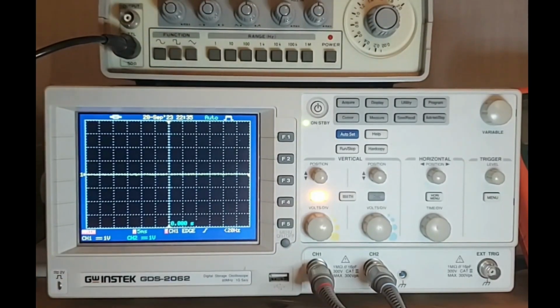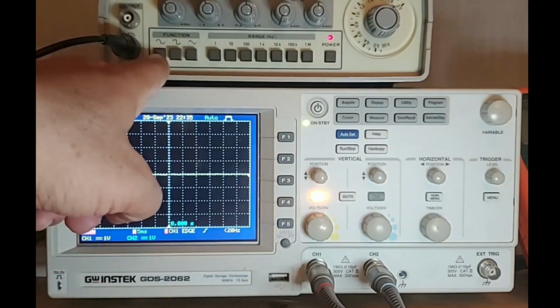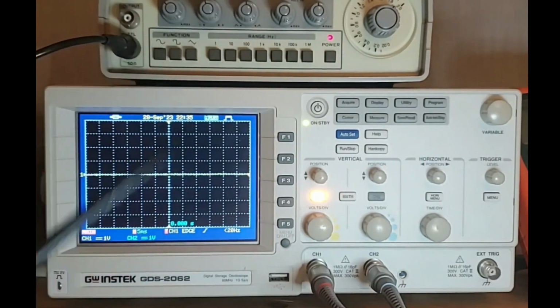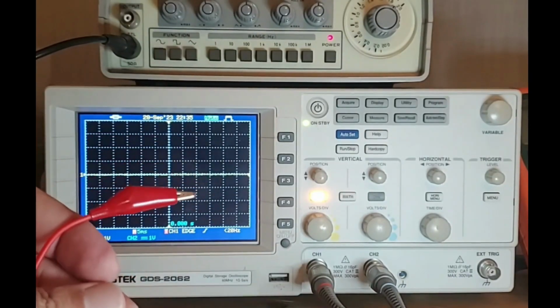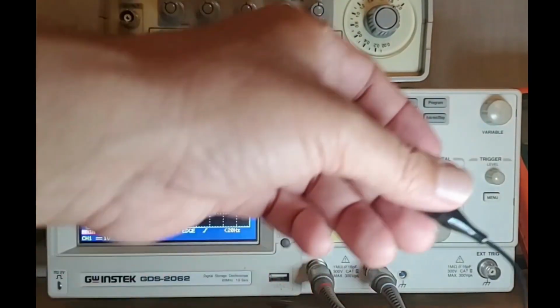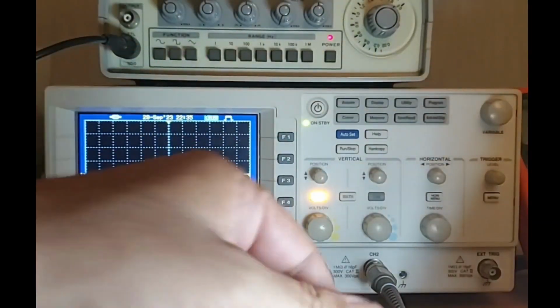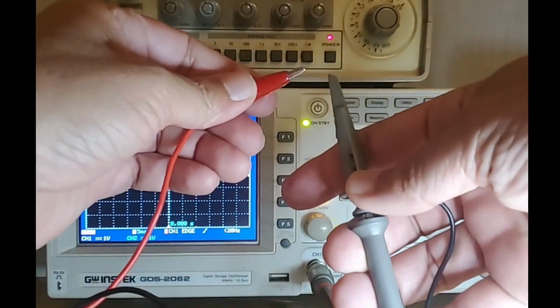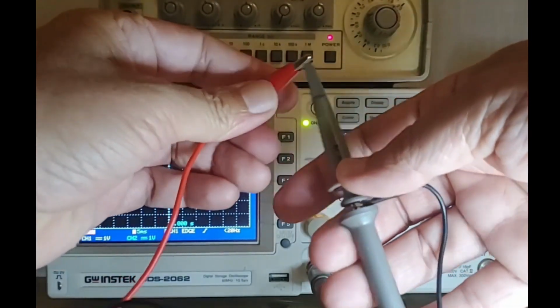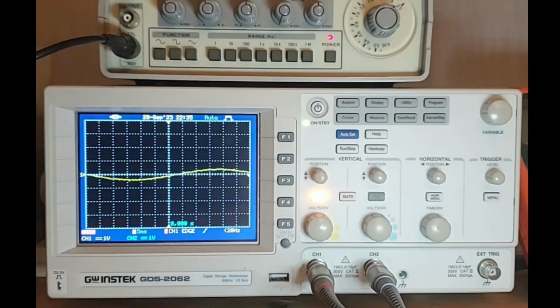So for that, I will turn on the function generator. I have selected a sinusoid waveform, and these are the probes of my function generator, and I will connect this to the oscilloscope. So I will connect the negative to the negative, and I will connect the positive of the function generator to the positive of the oscilloscope. And now you can see that I already see a waveform on the scope,